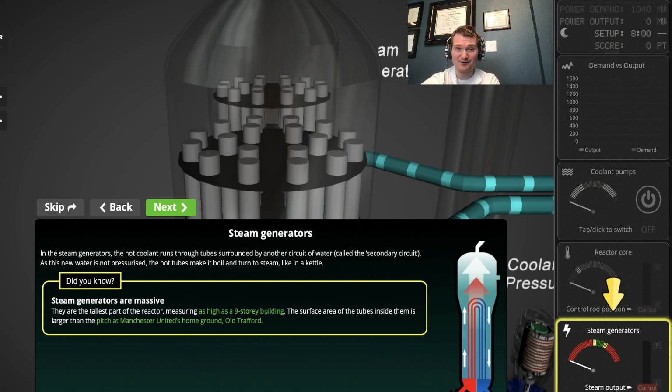And reactor power follows steam demand in a pressurized water reactor. So you increase steam flow by 5% of rated thermal power, reactor power is going to go up by 5%, and that's the end result. But you increase steam flow, reactor coolant temperature is going to drop, which is why you withdraw control rods to maintain temperature.